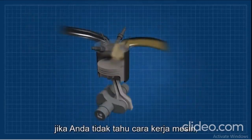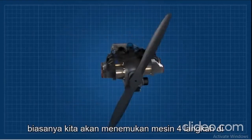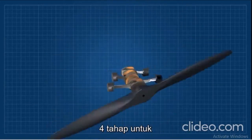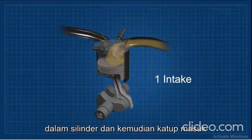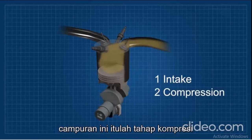If you don't know how an engine works, I'll show you real quick with this animation. Normally, we'll find 4-stroke engines in airplanes. This means that the cycle has 4 stages to complete. The mixture of fuel and air goes into the cylinder, and then the intake valve closes. The piston goes up and compresses this mixture.